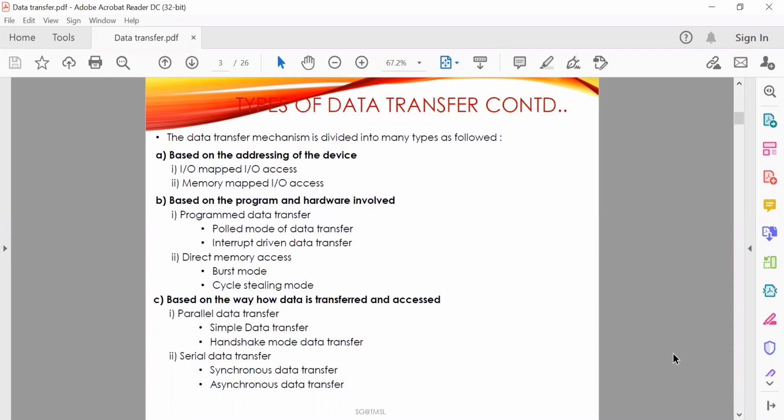So in general, a DMA controller can interface several peripherals that may request DMA with the processor. It is the controller that decides the priority of the DMA requests that are received simultaneously from many peripherals, and it then communicates with the peripheral devices and the processor and provides memory addresses for transferring the data. Normally one IC has to be used to perform this type of data transfer.